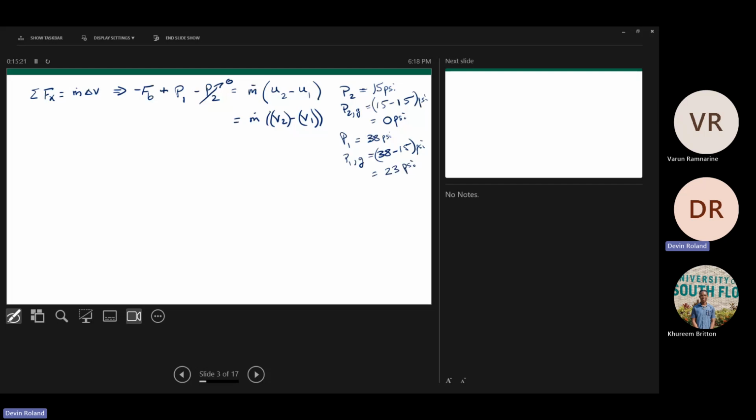Absolute pressure is the true pressure value, and gauge pressure is with respect to a baseline of atmospheric. Gauge pressure says the atmospheric contribution is assumed, and then we're adding on an extra amount of pressure.